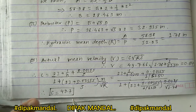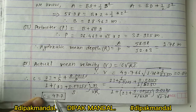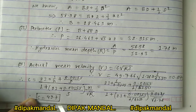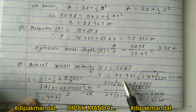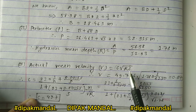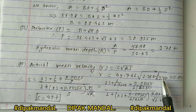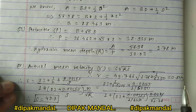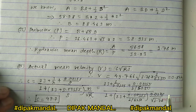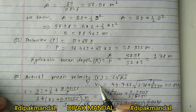Okay, and we have to use this value in this equation. After calculating this value of C, we keep it over here, so the velocity V equals 49.76, that is the value of C, root over RS. The value of R equals 1.78, and the value of S, that is the slope, is already calculated, 1 by 6250, and this value becomes 0.84 meter per second. Okay, after calculating.